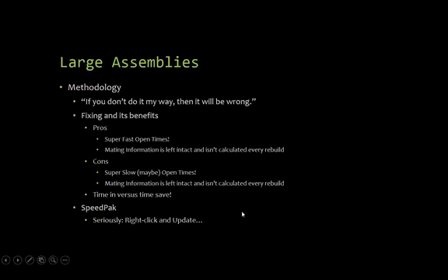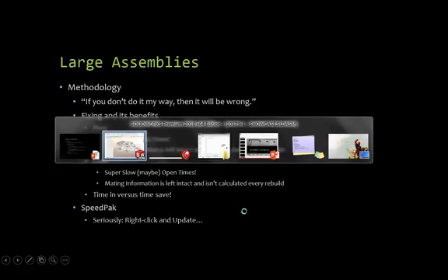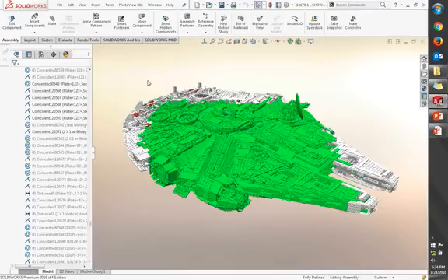Right click. I get about halfway through, and then I do a Control A, especially in a sub-assembly. Like I just did something real bad here, so don't look at the screen. You can do a window around everything, Control A, and as soon as you have everything, just right-click on one of the parts, say Fix, and all of them fix out for you. I'll work with a couple hundred parts, mating them together. But when I see my computer start to chunk a little bit, I window everything, right-click Fix, and it fixes out at that point.